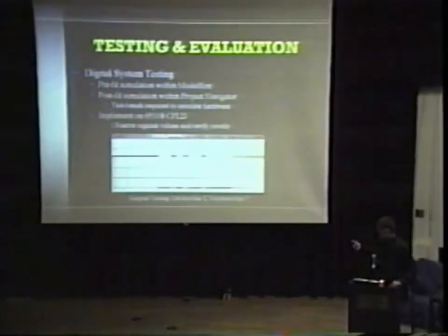the automatic high bit that's being read and the start pulse to 0. The device key 2 being hit gives a 2-bit word of 0, 1, which is right here. And function key 7 provides 0, 1, 0, which are these 3 bits here, a parity of 0, and the stop bit. This portion is basically the reset of the system back to initialization state. The register goes back to its original state.